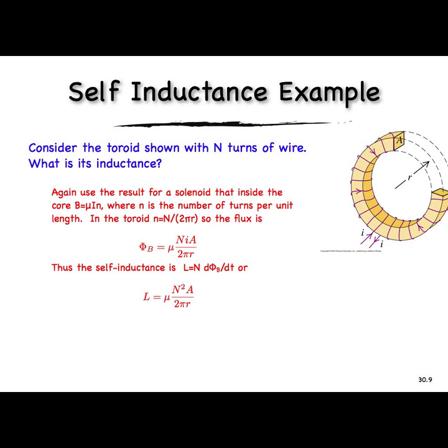So a coil of wires, I hate to use terms that are usually used for creatures and live beings, but it tends to want the current to remain constant. And the physics is such that it becomes difficult to change the current, because in attempting to change the current, the self-inductance produces an EMF that opposes that. So these coils of wire are used commonly to smooth out fluctuations in what should be a DC power source.